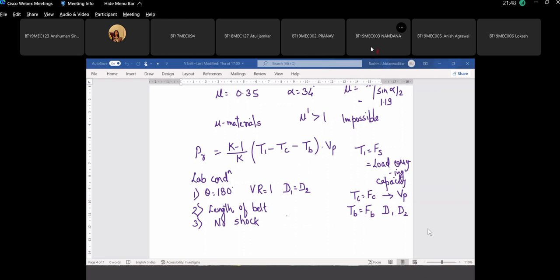What is the first table for V-belt design wherever it starts in your book? Mine is 7.58. What is that first table indicating or showing? Standard sections. So you are getting cross section for the symbol A, B, C, D, E. Then you are getting usual load on the drive. Then recommended minimum pulley diameter, nominal top width, nominal thickness, and the weight per meter of the belt, right?